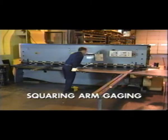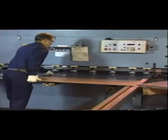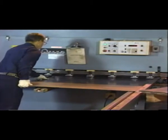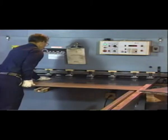Squaring arm gauging, with the squaring arm mounted on the end of the shear, enables the operator to shear a 90-degree corner on the material. The squaring arm can be mounted on either end of the shear to distribute wear on the knives.